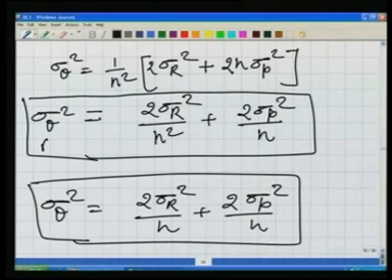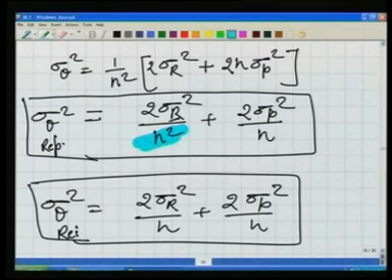In the case of the method of repetition and reiteration, the error which is propagated into our final angle, that we are writing by sigma, the standard deviation of the error, in both the cases is dependent upon the error due to reading and the error due to bisection. However, as you will notice, for the reading, the term here in the case of the repetition is n square, while in the case of the reiteration it is n.